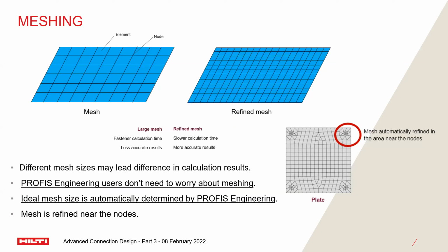So I think the last thing that I want to mention on this one is meshing. All the finite element components and the attached members are held in place by a process called meshing. The process of meshing helps ensure the plate elements are properly connected at the nodes, if you remember one of the very first slides where I explained this, and all the components are rightly placed where they should be as per the model. The FEM or FEA program will automatically optimize the design by choosing the most appropriate mesh setting for you. But again, you have the option to go in and change the mesh settings if you want. But again, our recommendation is to stick to what's in the program, which gives you the most optimized design anyhow.